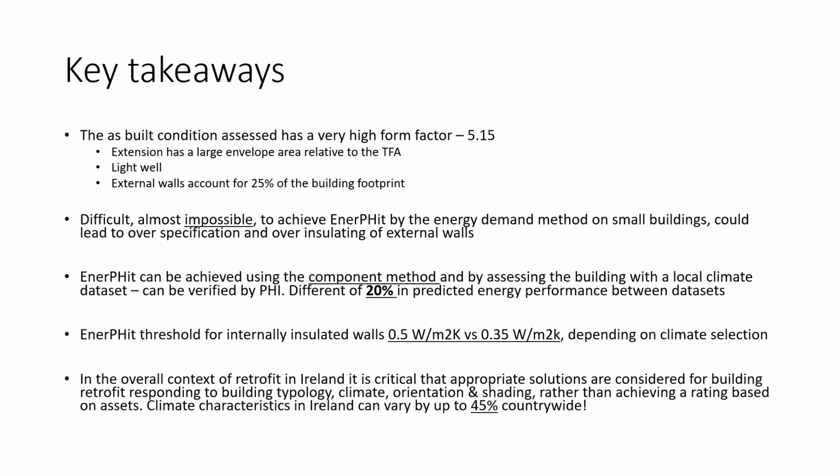And it's a vital thing to consider, because when you fold out those areas, those light shaft walls are accounting for 2.5 meters squared of your envelope. And in some buildings, you might have quite a few of them. If you're insulated on a flat ceiling, and you have your roof windows, they can be quite significant, and they are also adding to your form factor of the new building.